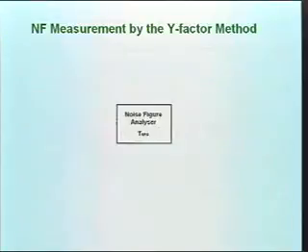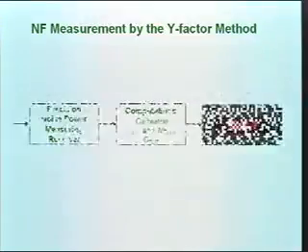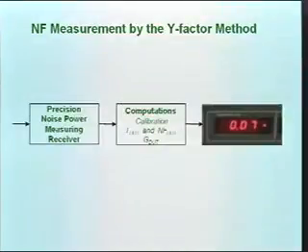Looking at the noise figure analyzer more carefully, what we have is a precision noise power measuring receiver, and David will tell you more than you would ever want to know about this, followed by some computations which take care of the calibration and calculation of the two things you usually want to measure, either the noise temperature or the noise figure of the DUT. Choose your units. That's your choice. And the gain of the DUT. And finally, it's displayed.